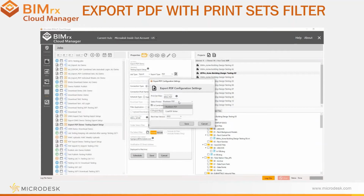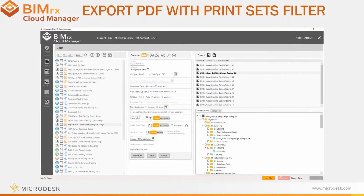in the export job. Next, I select the printer, Bluebeam if you have it, or a free PDF printer option is also provided. I can choose if the PDFs are printed as individual sheets or if they should be combined into one file per print set. Next, I'll set the export destination and then select the Revit version year and then save the settings.